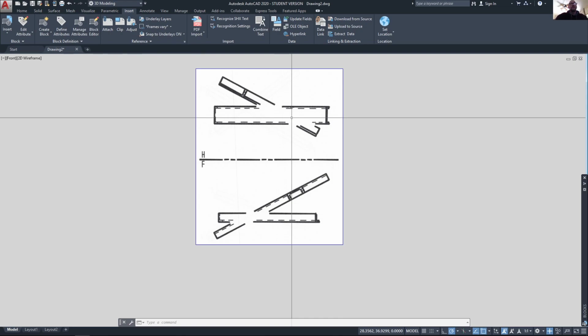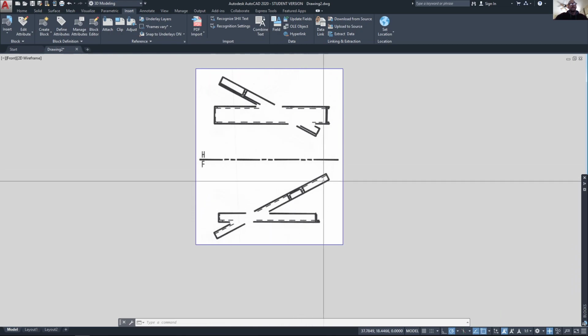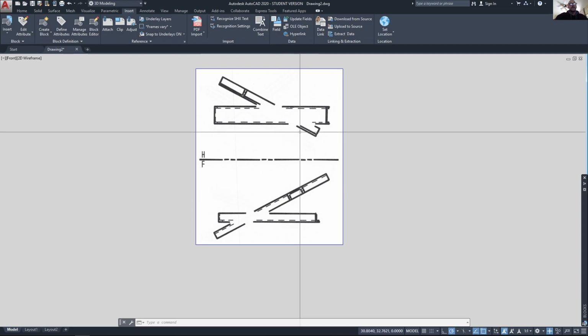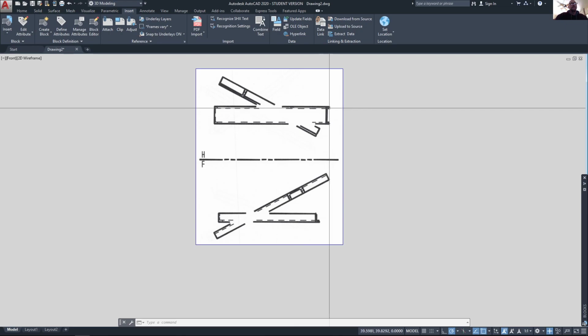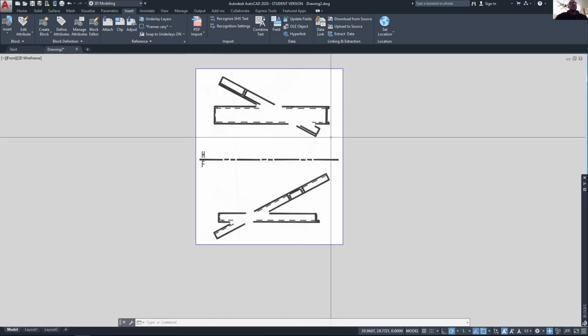Then I'll follow the vertical line to the front view and look at which beam is actually closer to the horizontal plane. Looking at it in profile or in the front view where I can see elevation, I can see that this angled beam in the front view is higher at that point of intersection. So looking in the top view, I ought to see, apparently it would be this C channel. It looks like it's a C channel. Then we'll take some measurements and actually do this in 3D so we can kind of see it better too.